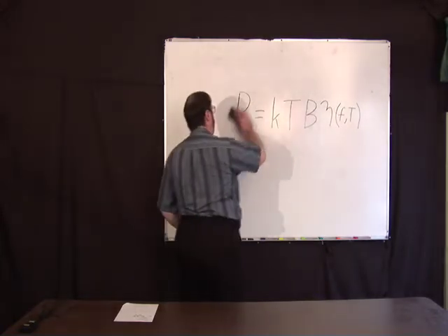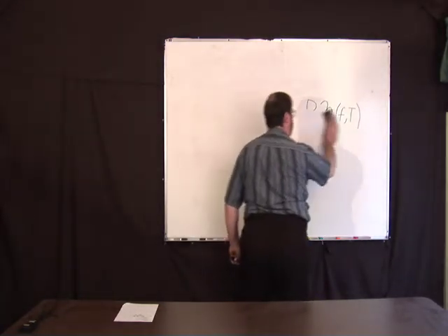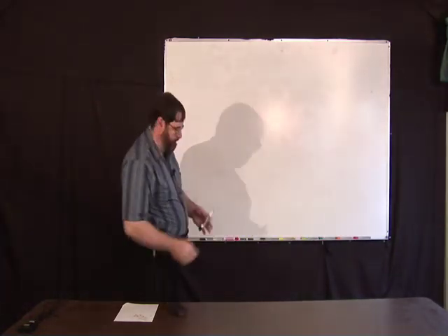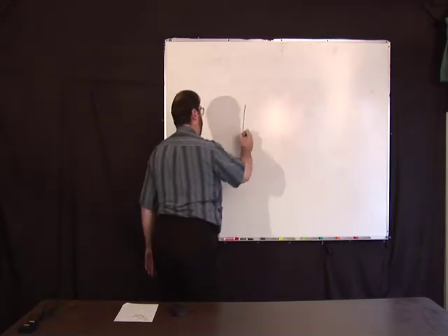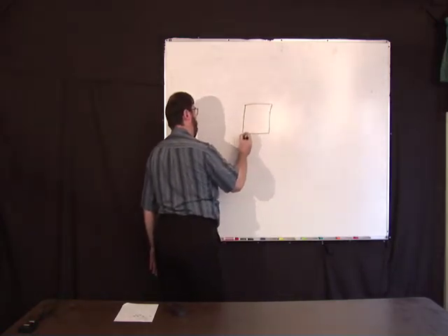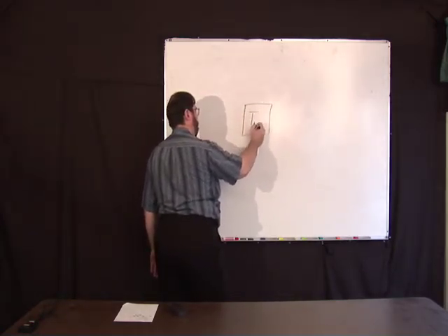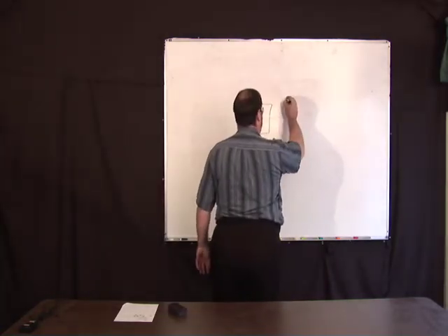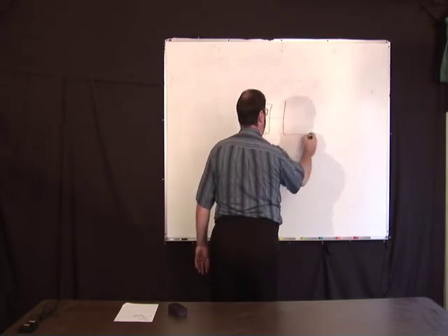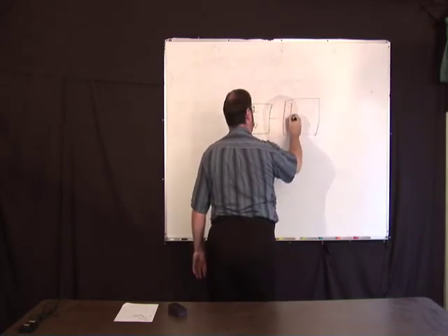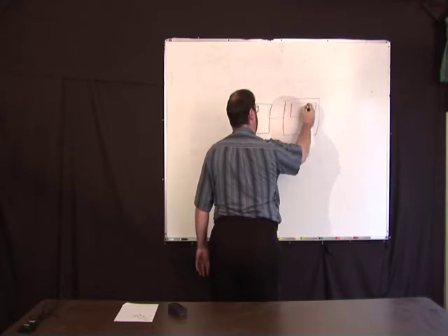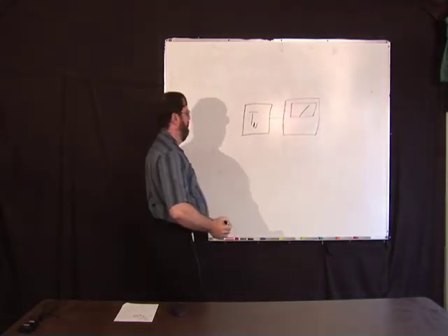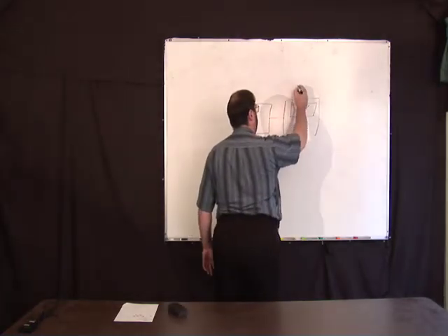But we're going to go back to this. We're going to talk about measuring it now. Now, how you make a noise measurement system. Okay. Let's say you have some noise source at some temperature. Let's call it T, some noise temperature. You want to measure the power per unit bandwidth, or just the power in a given bandwidth, so you can compute power per unit bandwidth. You have some power meter of some sort. Okay, you're going to measure some power, PM.